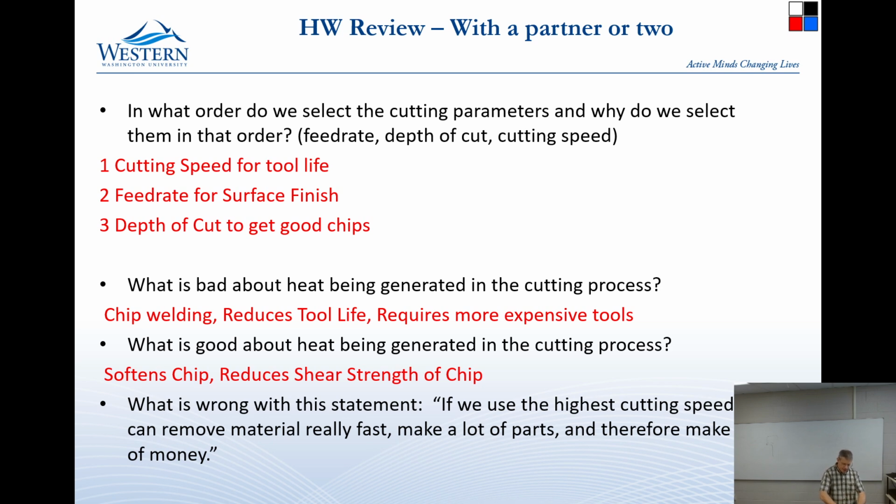What will happen is, instead of cutting, the cell will start to collapse, and it just keeps rubbing the tool, rubbing the tool, rubbing the tool until it gets all the way to the other side of the cell, which strengthens it a little bit, enough that it'll get cut and the little flaps will come out. But for the entire width of the cell, all it does is rub the tool and create heat.